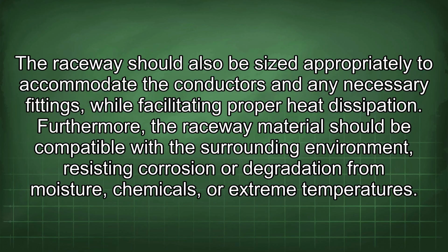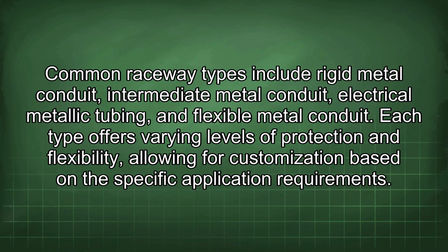Furthermore, the raceway material should be compatible with the surrounding environment, resisting corrosion or degradation from moisture, chemicals, or extreme temperatures. Common raceway types include rigid metal conduit, intermediate metal conduit, electrical metallic tubing, and flexible metal conduit. Each type offers varying levels of protection and flexibility, allowing for customization based on the specific application requirements.